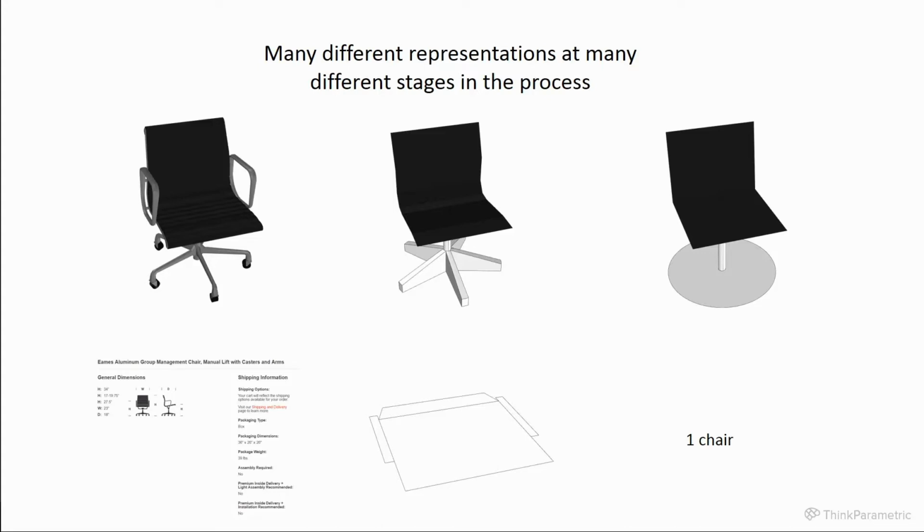Each object can be represented in many different ways. Different trades need different aspects of an object. For architectural renderings, you'd want the models to have the most detailed geometry possible. Materials as well as textures need to be assigned. For basic indication of the object in space, you could do with a much lighter version of that model. In order to determine, for instance, sidelines from chairs, you only need access to the seating surface at the correct height. Some parties in the process just need to know properties of the object, such as dimensions.